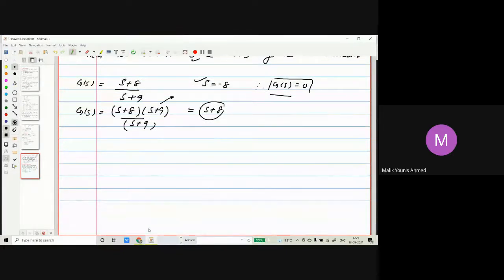So in control systems, we often refer to the roots of the cancelled factor in the numerator as zeros, even though the transfer function will not become 0 at this value. However, we will include this because there are reasons I will tell you once we do our time domain analysis. We'll see what effect a pole and zero have there. So next is poles and zeros of a first order system.